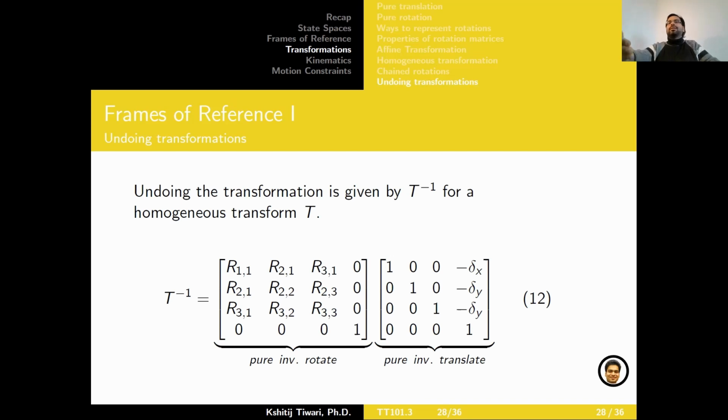So that's like +3 or -3. That's what the minus sign before the deltas represents. And while you're doing this, you're not doing rotation. That's why the rotation component, the block, is represented as an identity matrix here. The same thing on the other side: when you're only doing rotations, your translations are all zeros and you're doing the inverse rotation. So your inverse rotation matrix is the transpose of the rotation matrix.